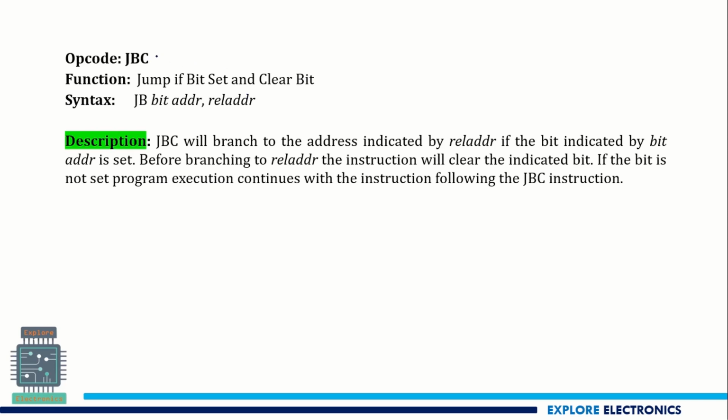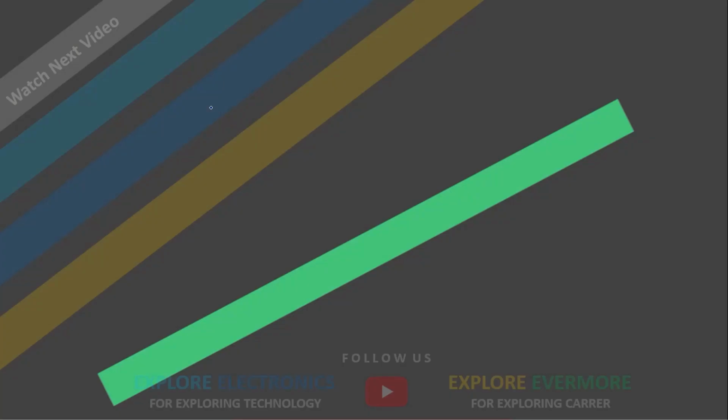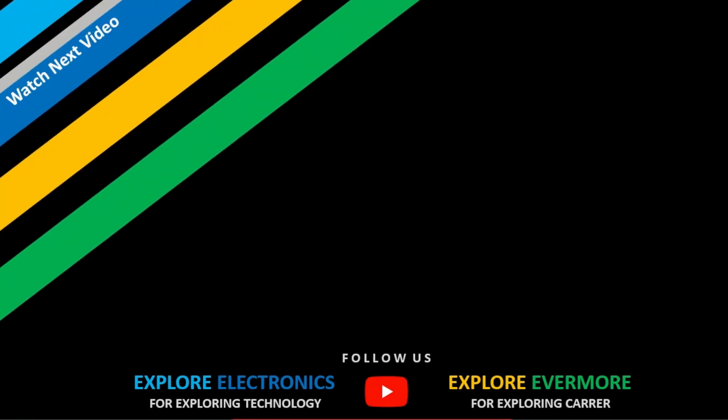Then we have JBC, jump if bit is set and clear the bit. Here you have an address to jump to, and it will check whether the bit is set or not. Before branching to this address, this instruction will clear the bit of this address. It will make it 0 if it is 1. It checks if it is 1, then it knows that we need to branch to this address, and it makes that address bit 0. This is JBC. So these are the different instructions we are going to use in microcontroller coding.